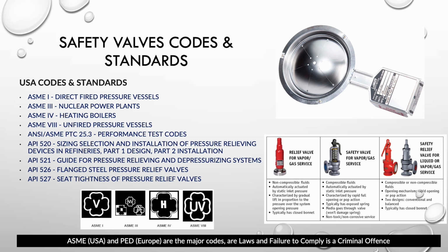This is pretty much a pressure vessel, but it's not exposed to flame. The reason you have two segregations between fired and unfired is because the overpressurization scenarios are way more extreme when you're exposed to a heat source versus something that's just containing internal energy. So that's the reason why you have this type of standards.